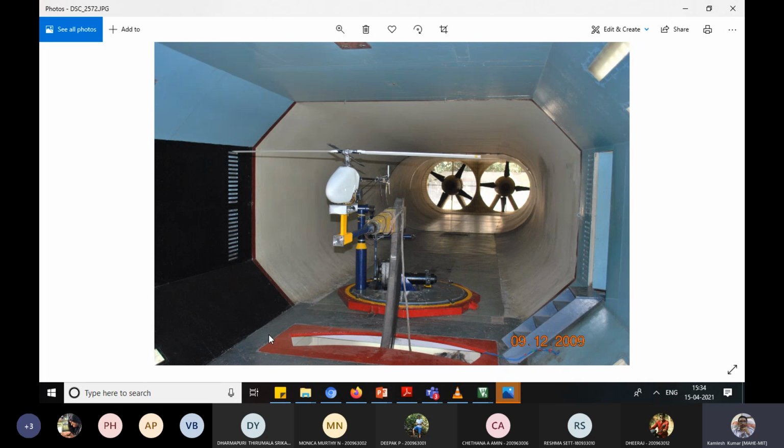And the other thing they can do is yaw also. So mostly they are looking at the side slip as well as the yaw angle. So they can change here. Not just angle of attack, but side slip also you can get. Angle at least you will get. Roll facility is not there. If you want roll, then you should have another setup here which rotates, which means you can rotate your models.